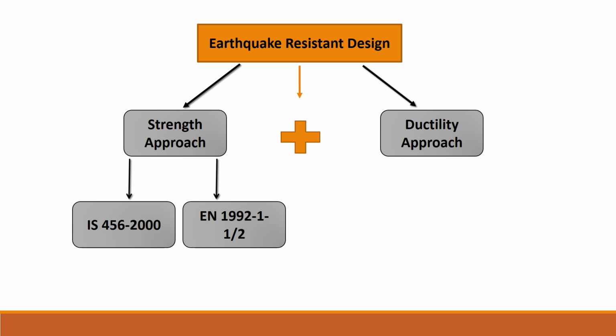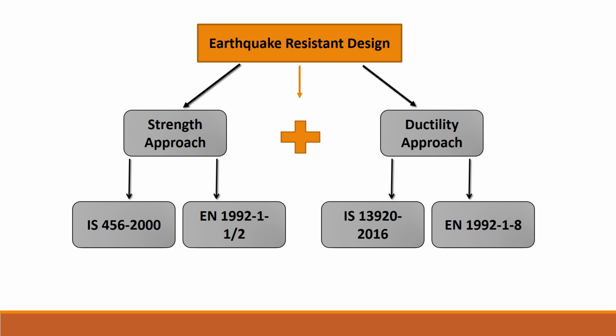Now, the ductility approach we'll be studying in detail in this lecture. It's given by IS 13920 2016 code in India for structural design. This code takes into account the ductility approach for earthquake resistant design of structures. In Europe, the code EN 1998, which is meant for earthquake resistant design of structures, considers the ductility approach for the structures. Now, what is the ductility approach of structures?